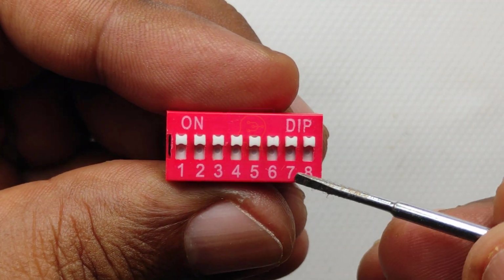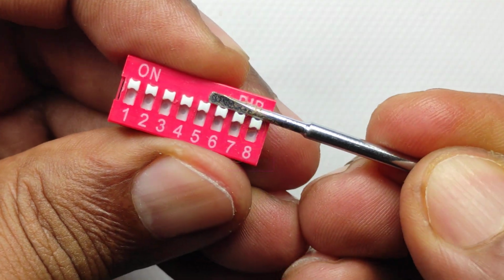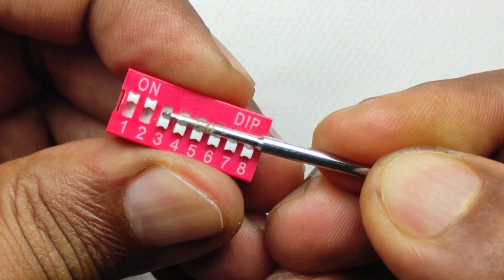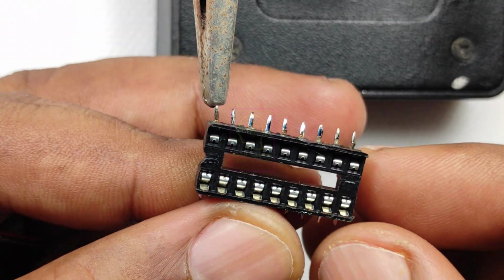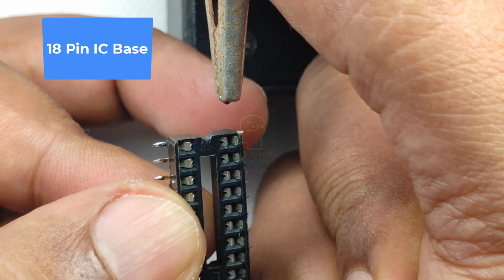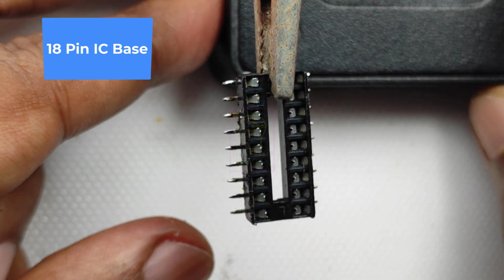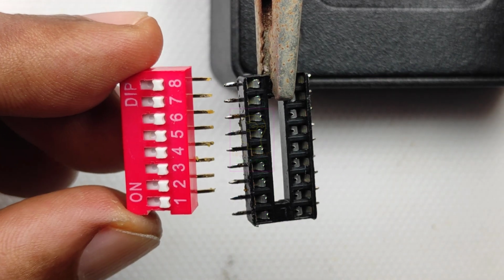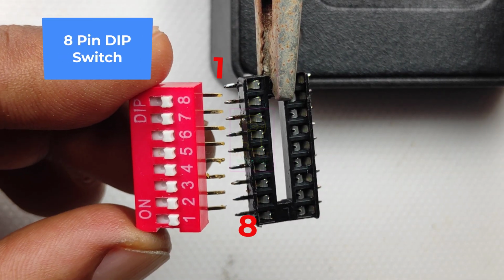All ICs and modules which are used in these circuits are working on 5 volt only. So please be alert while powering this circuit. We will first assemble the transmitter section and later we will assemble the receiver section. I prefer to use a common PCB for assembling the components rather than soldering directly to the component leads. But for newbies in electronics, I am doing this for you. For experienced people, I have added the circuit diagram at the end of this video.